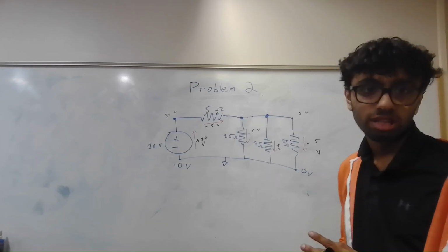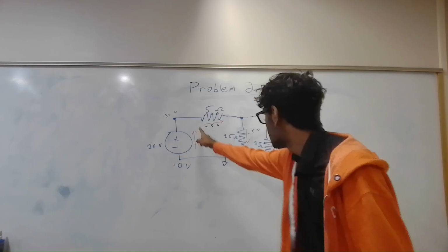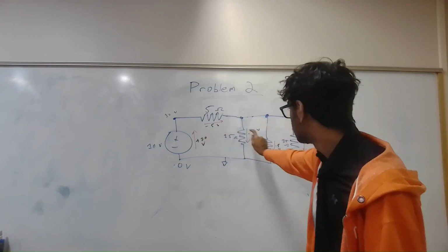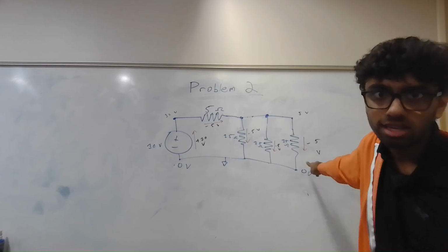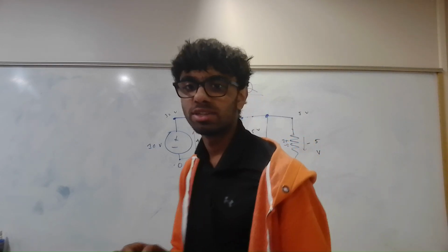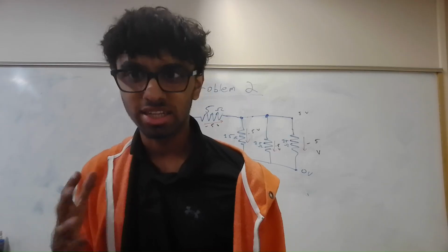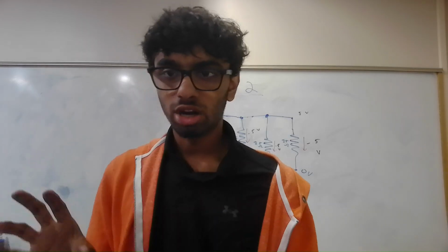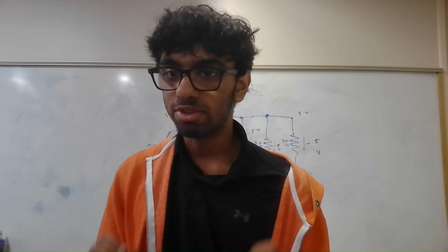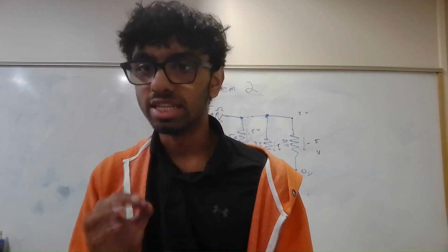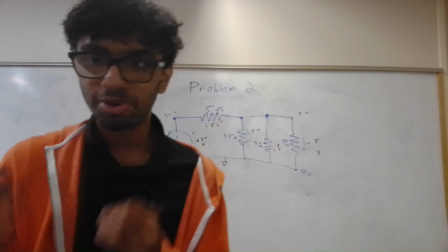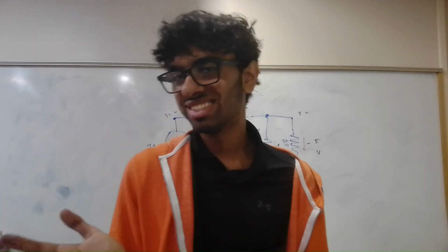And step 2 is to add them all up. So 10 minus 5 is 5, minus 5 is 0, minus 5 is negative 5, minus another 5 is negative 10. So negative 10 volts is the total. And this is what we discussed in class. The voltage gains and drops do not necessarily need to add up to 0. The powers supplied and dissipated need to add up to 0, because power is about energy, voltage is just potential. It's not necessarily energy.